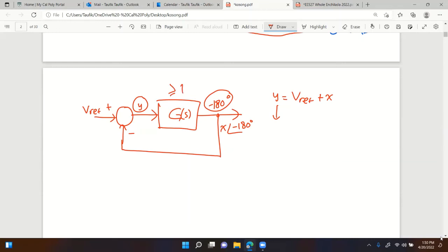right? Because then the signal right here, the output basically, V out, here V out is equal to 0.01 times y, right? So anytime it goes back, you always multiply by 0.01, so it becomes smaller and smaller and smaller. The error signal becomes smaller and smaller and smaller. So that's okay. But if you always multiply by 1,